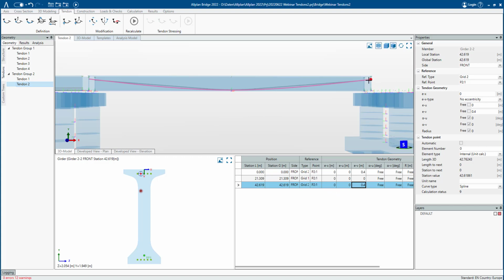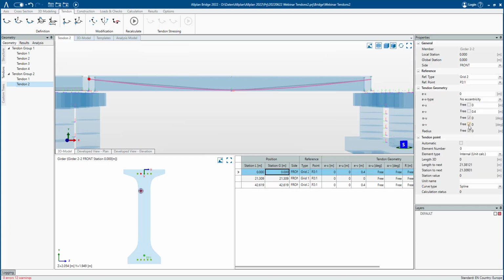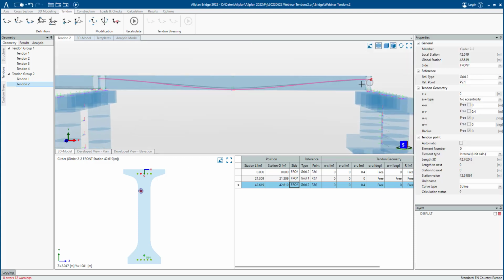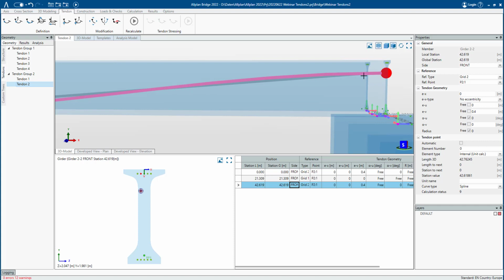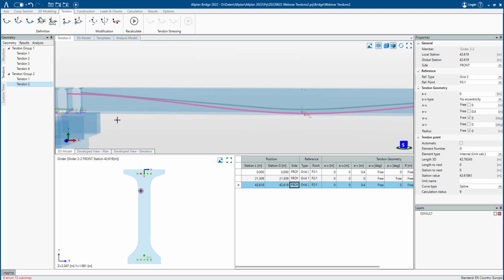Another thing here at this point, for the constraint of the angles, I can also say if I want a certain angle at the end, or for example I want to have it horizontal, just go to the respective one, in this case the V direction, alpha V. I set this to 0 in the end here, and also set it to 0 here, and as you can see I now have a horizontal tangent there and there.